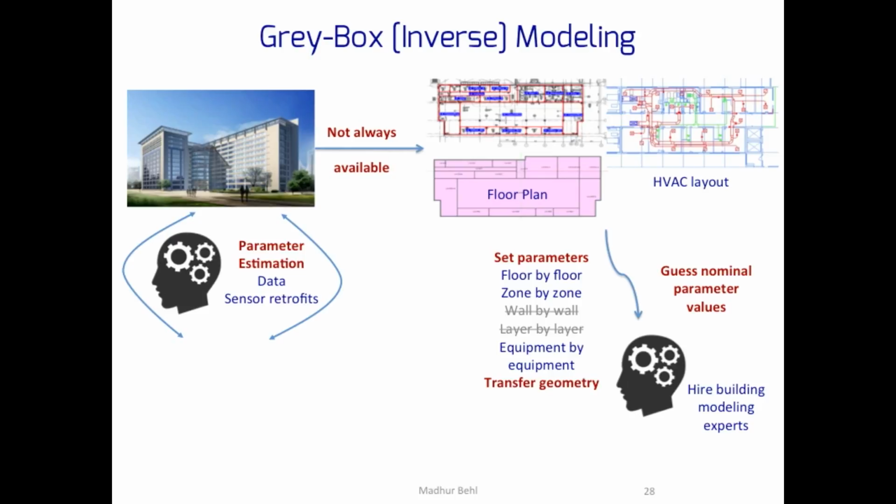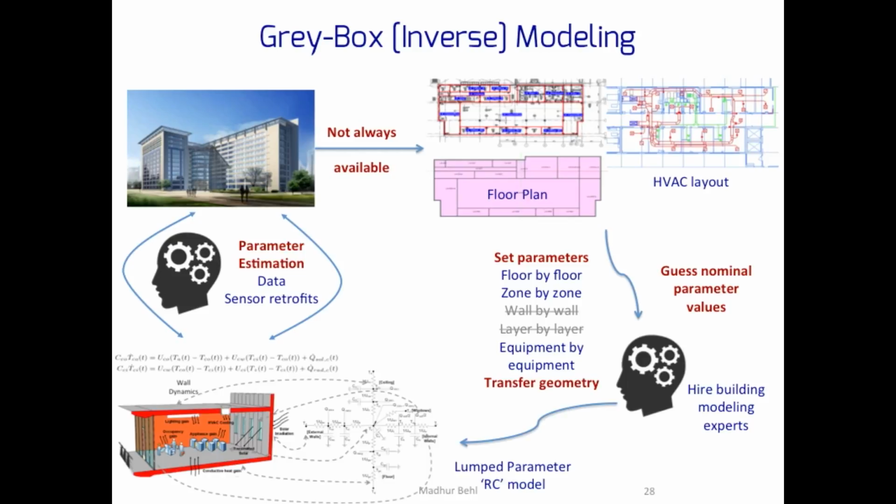The first is that we won't model the building in very fine detail. So we have some level of abstraction in which we want to model the building, but still the domain expert, instead of tuning parameters of a building simulation software, has to set up a mathematical structural model of the building itself, still relying on first principles of physics, and then tune or learn the parameters of this mathematical model from real data from the building.